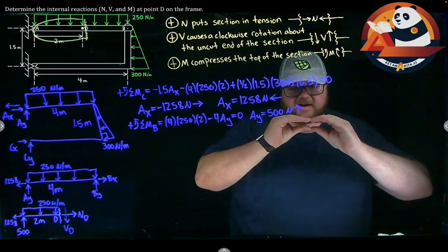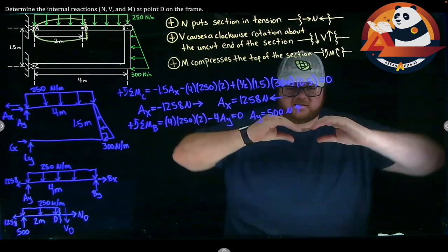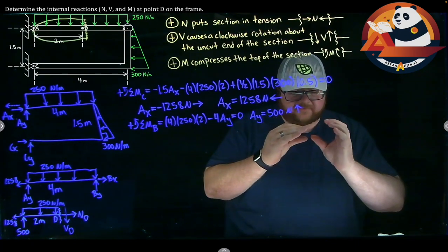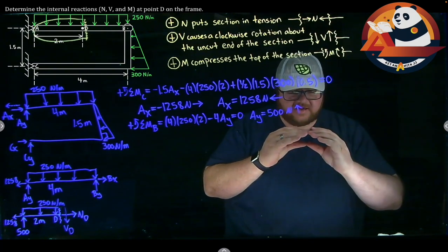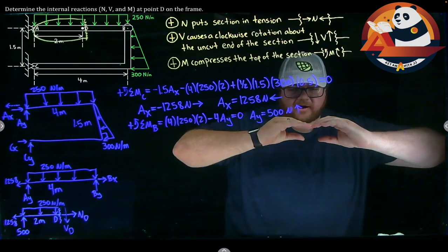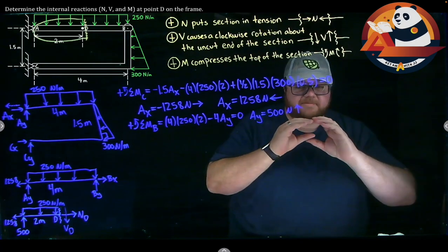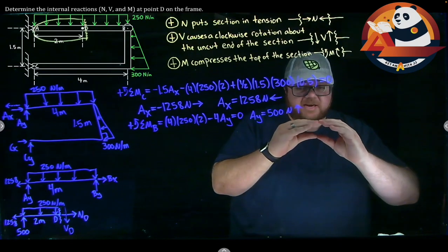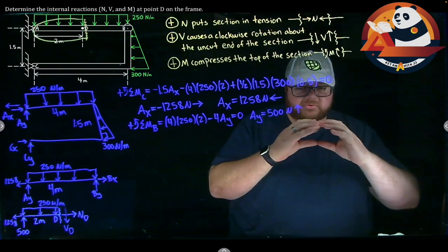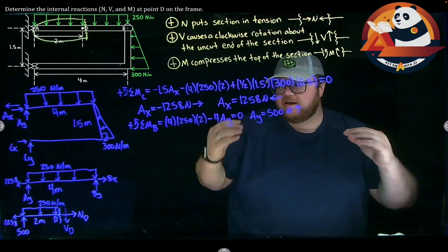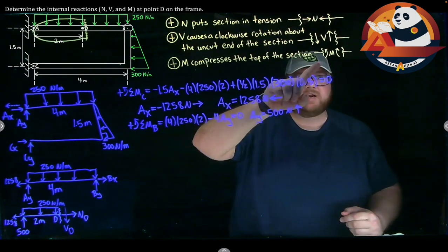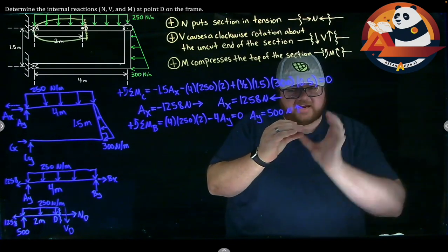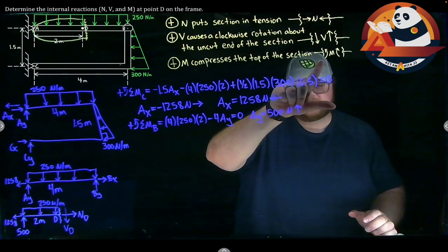If you think of holding your hands together like this, if I try to bend, in either direction here, if I bend and lift my elbows up, really I'm putting a counterclockwise moment on this. My thumbs at the bottom spread apart. If you're thinking through what's happening on any material, if it's starting to pull itself apart, it's in tension down there on the bottom. But at the same time, my fingers up on the top are starting to squish into each other. They're compressing in. That's putting my fingers into compression when I have that counterclockwise moment on the right edge of my hand.